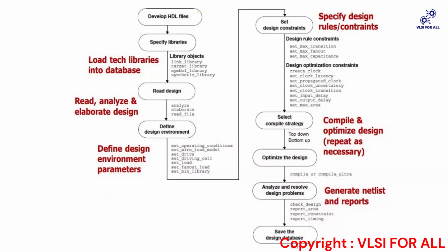With report QOR, you can check the quality of your design, like DRVs, static power, and compile time details. In report timing, it gives pinpoint information on clock paths and data paths that have the worst slack, along with delays and slack calculation.